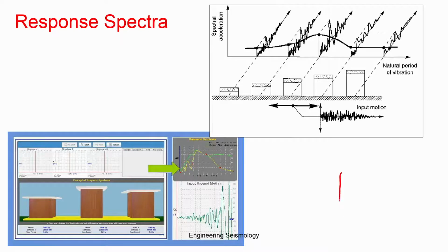A single degree of freedom system is generally assumed as a single pendulum with mass. The damping and other things you can incorporate, but this is the simplest form you can assume. So, you take the maximum response of this for a given input by changing its natural period. The height will decide your frequency, you give a typical input and then you measure a response. That response is called a response spectrum.